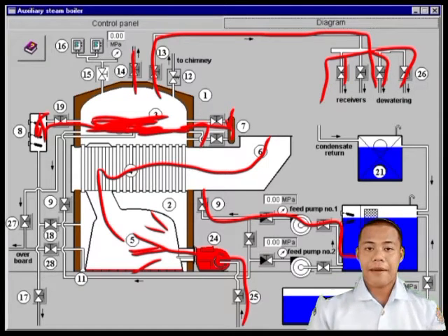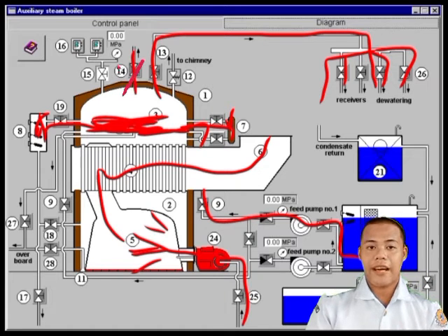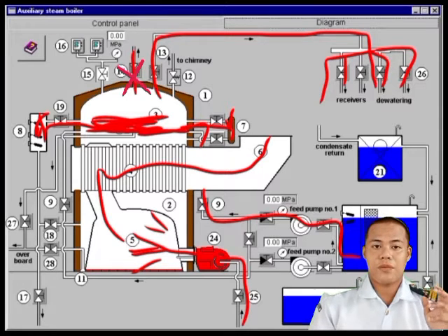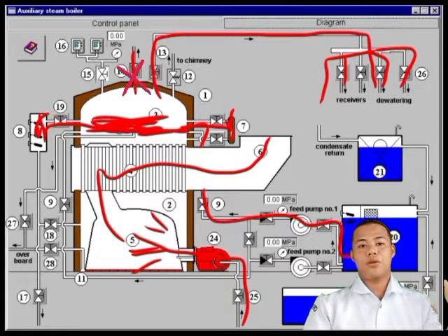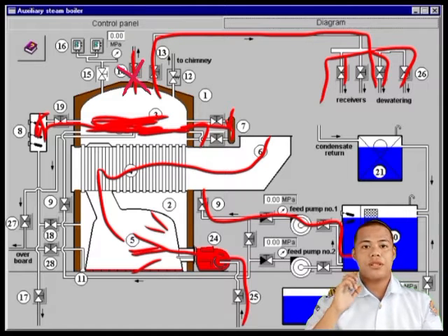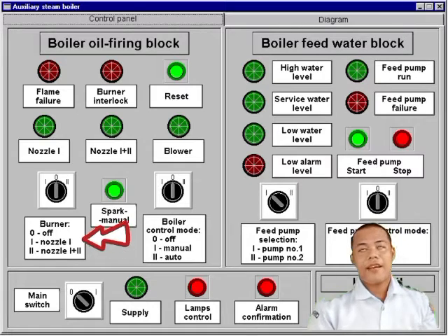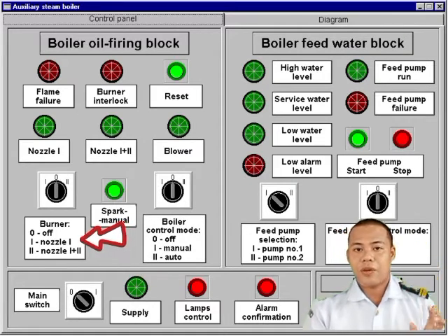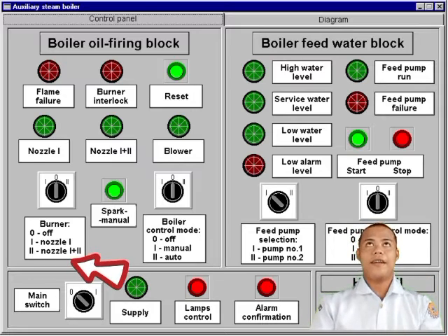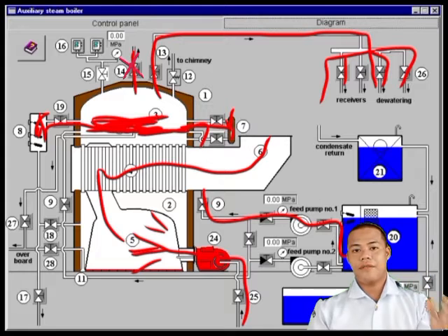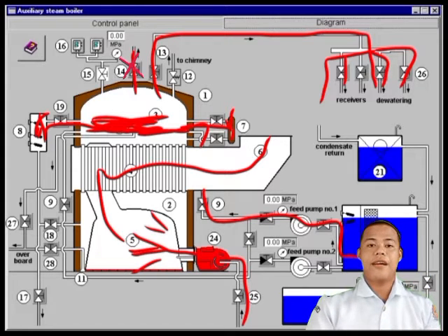it is time to close the air vent and stop the intermittent firing, and proceed to continuous firing to produce greater firing. Then in order to produce greater firing, go to the control panel, then change the nozzle into +2. Then the increase of steam is created, and the pressure of the steam inside the boiler can also be read